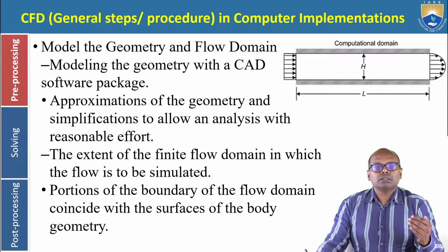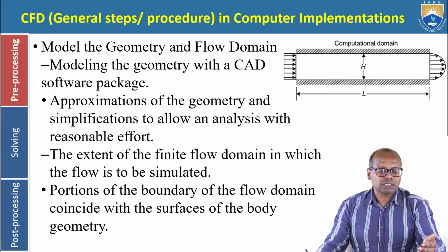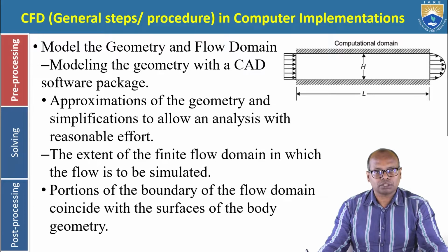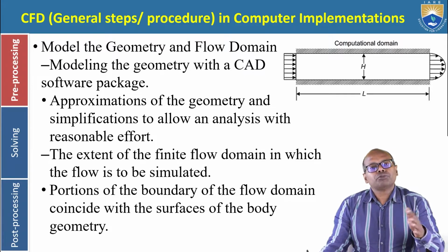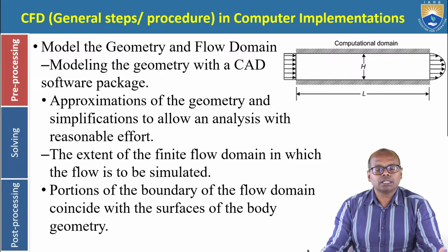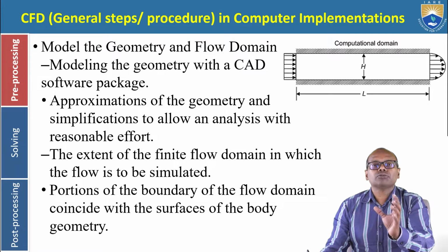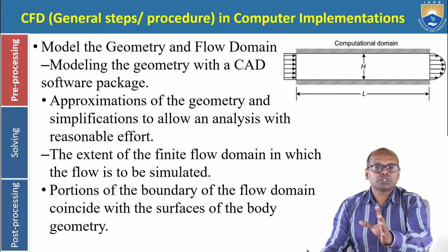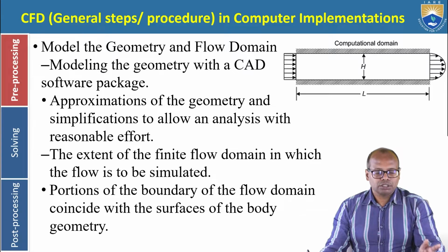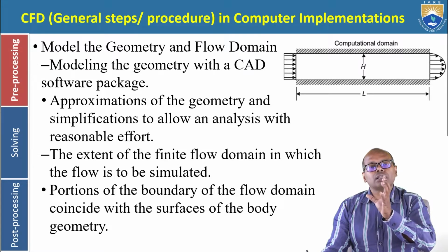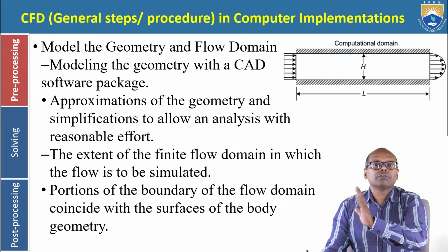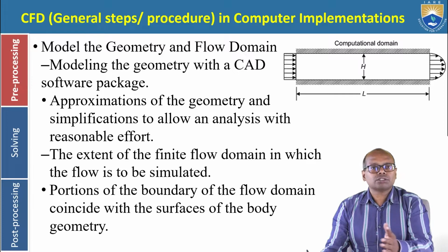Now in CFD, we have three things called pre-processing, processing, and post-processing. Pre-processing means before starting the simulation, we have to create the model, we have to do the meshing, we have to give the solver inputs. All those things come under pre-processing. The solving or processing means, once all the things are established inside the black box, we start the run and it will solve all the governing equations at different points of the grid. So that is the solving process.